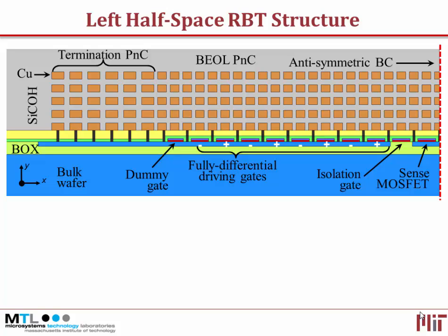So this structure, everything seemed fine, and we expect to get very high Q after limiting the leakage of the wave. But there was a big challenge. Once you have a waveguide in solid material like that, and you start terminating it, you get two things. You get specular reflections, that's reflection normal to the incidence, but also you get scattering, which is radiation, or you can say it's coupling to other modes along several other directions. So the moment we basically terminate this waveguide here and add this isolation, we started finding leakage at this point. Basically, the wave started radiating in all directions.